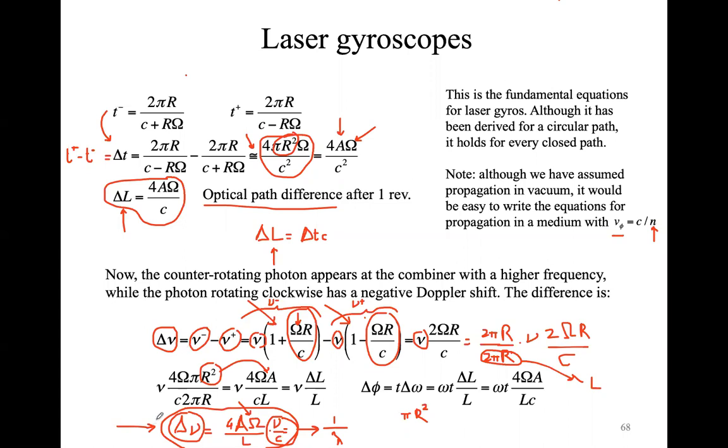One of the main differences is already clear because, as I said, ring laser gyroscopes usually deal with delta frequency. So we have a delta nu given by this expression here. When you want to deal with the fiber optic gyroscopes, you usually use delta phi, the delta phase of the two-beam interference. Delta phi, as you know, is delta omega times t, where delta omega is related to the frequency, the pulse rate.